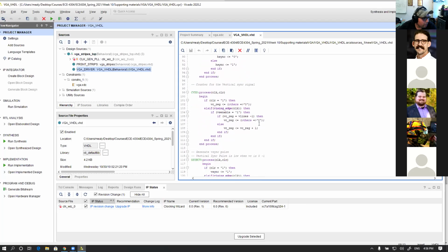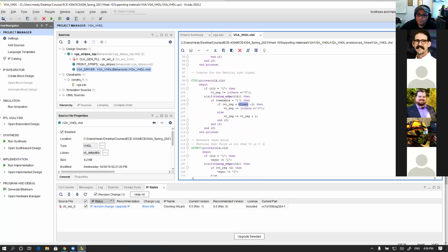Yes. So now, if the vis enable is 1, that means I finished the first scan of horizontal. I will start looking at the maximum vertical. If it is the maximum vertical, do what? Reset, that means round back, because you have to do this all the time. It's continuous. Else, just count. Just count when enable is 1. That guarantees every tick the counter will be incremented, which is aligned with my story.